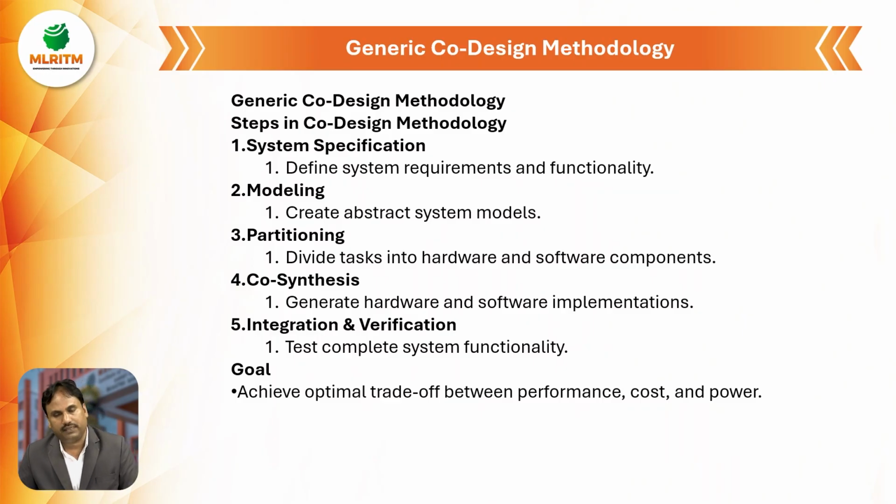So, generic co-design methodology, steps in co-design methodology. System specification defines system requirements and functionality. Modeling creates abstract system models. Partitioning divides tasks into hardware and software components. After that, co-synthesis. So these are all steps in co-design methodology. System specification is required, after that modeling, then partitioning. Co-synthesis means generating hardware and software implementations, and integration and verification tests complete system functionality.